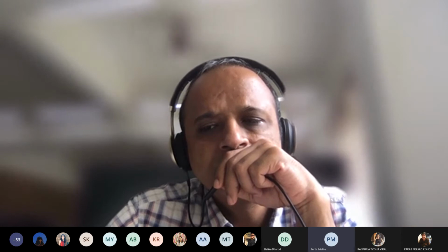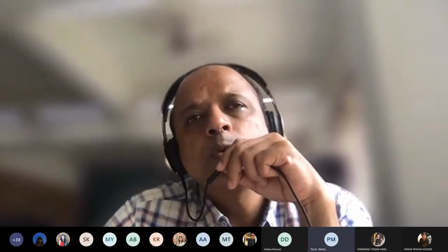Yeah, hi Vikram. So I was thinking about our structure, the One World Trade Center in New York. We don't have much information regarding the seismic activities or how the building reacted to them, because there isn't much information about the basement. But what we understood from the information they gave us is that the central core is made up of a special concrete that is extra hard. So any lateral loads that are coming, like the wind loads, are negated by the core itself, by providing more stiffness.